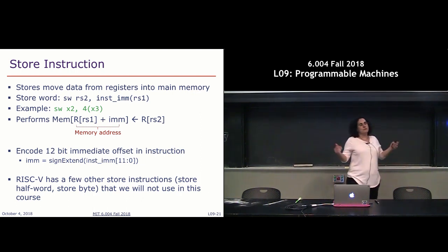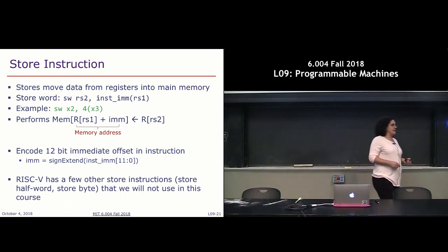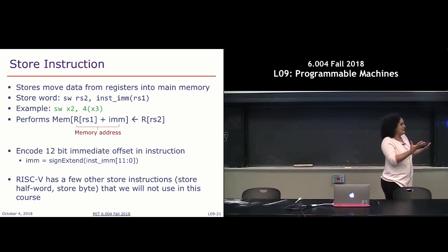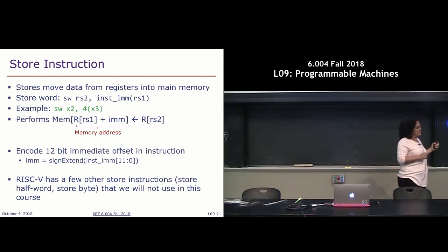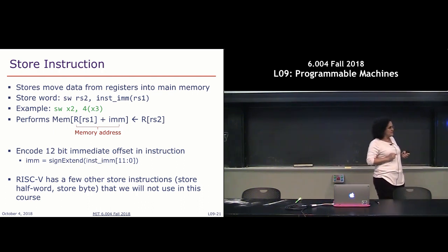So for example, suppose that my address was 0x100. What it's telling you is that it's going to load everything that's at address 0x100, 101, 102, and 103. It's going to load 4 bytes worth of data into this 32-bit register. But I only specify load, what's at address 100, and by default, that's going to load 32 bits.